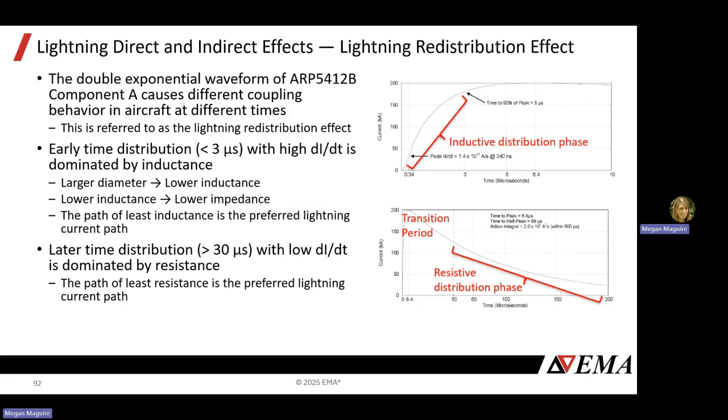Why this is important to take into account for your modeling is if you're doing magnetostatic scaling to try to take advantage of increasing the time step and decreasing simulation time. You'll want to have a lower rate of change for your permittivity in the earlier part of the waveform, because the earlier part of the waveform is not magnetostatic or quasi-magnetostatic, whereas you can have a higher rate of change of your epsilon value at later times when it becomes resistively dominant and magnetostatic, or essentially magnetostatic.